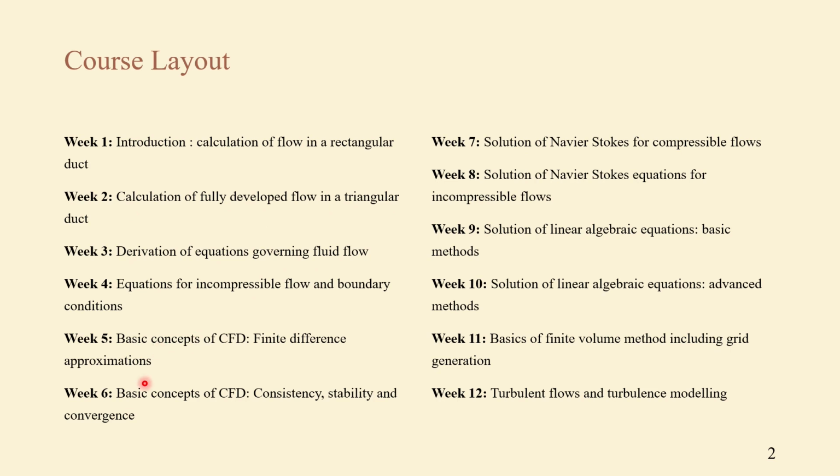Week 5 and week 6 are about basic concepts of CFD, basically finite difference approximations, and criteria like consistency, stability, and convergence, which we need to know to have a complete knowledge while solving those equations, because the ultimate aim is to get the solution. For that, the system needs to be consistent, stable, and convergent.